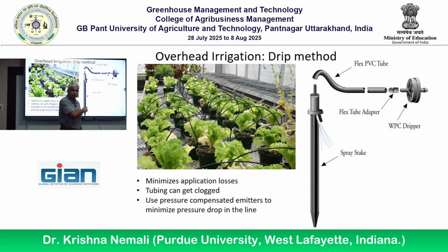Before you use this drip system in parts, before you place parts, first set up the drip system like I described, with all the emitters, capillaries, however you want it, manifolds and everything. But let's say you have a greenhouse of this size. In this size of greenhouse, you know what I will do? I will take maybe 10 or 15 empty buckets, or beakers, something like that, plastic buckets, and I will put them randomly, one over there, randomly distribute them. Put your drip emitters in there, empty ones, you know, these drip stakes right inside, and run your drip system for 5 minutes. And then go and measure the water.